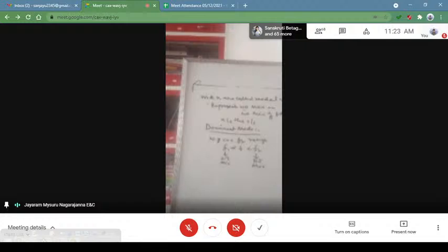The least frequency supported by the waveguide, or the longest wavelength supported by the waveguide corresponding to a field pattern, is called the dominant mode. So if you have a frequency range of 1 gigahertz to 10 gigahertz, 1 gigahertz is the lowest frequency for that band, so it corresponds to the longest wavelength supported by the waveguide.